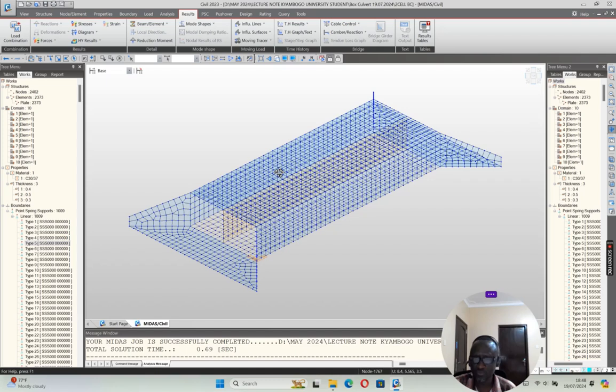It is going to create more weight, reduce the uplift pressure, which is buoyancy, and the structure will remain safe at whatever weight it has, because the rock fill already has an advantage by adding weight, suppressing the buoyancy effect. So I think that is what we would do, and therefore I'm going to quickly use some arbitrary values of load. No, you have to generate them.